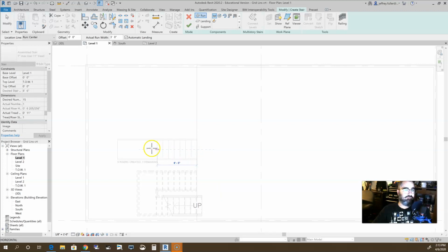Of course, it's drawing from the center of the stair, but I want to switch back, and I don't want to have this gap in there, but I really don't know where to put it in order for that gap not to be created. Okay, so I'm going to change the run. It says run center. I want to do what's called run right. So it's going to use the right side of the stairs to actually base its start and end points on.